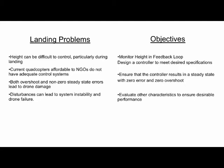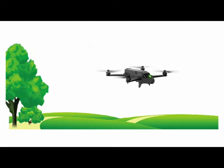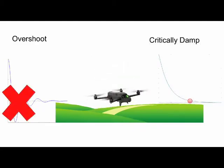As the quadcopter lands, if it comes close to the ground and the system is designed with overshoot, you can get crashes. Our optimum control system will be a critically damped system. In a critically damped system, we would see a longer rise time and a longer settling time, but no overshoot, providing a safe landing.